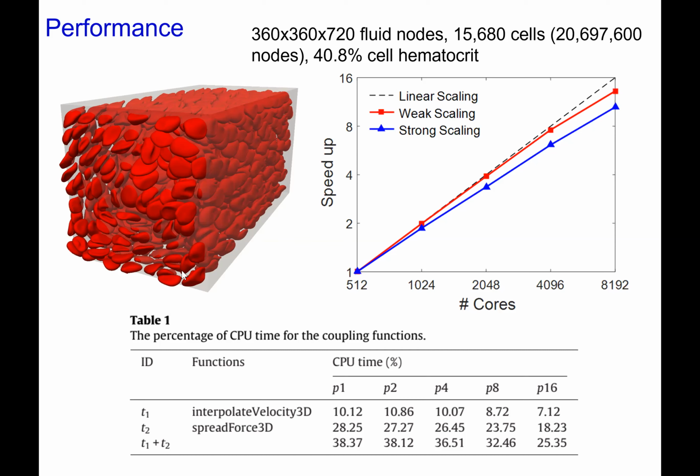If you use OpenFOAM or even FEniCS or DOLFIN, there are a lot based on finite element, finite difference, or even finite volume method. Eventually, you get a big matrix, right? You have all those unknowns to solve. You have to solve big matrix problems. Even if you can use different preconditioners and very fast linear solvers, you still have to solve that linear matrix problem.